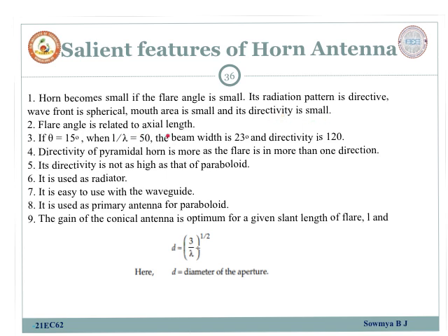The flare angle is related to the axial length. If theta is equal to 15 degrees, when l by lambda is equal to 50, the beamwidth is 23 degrees and the directivity is 120.